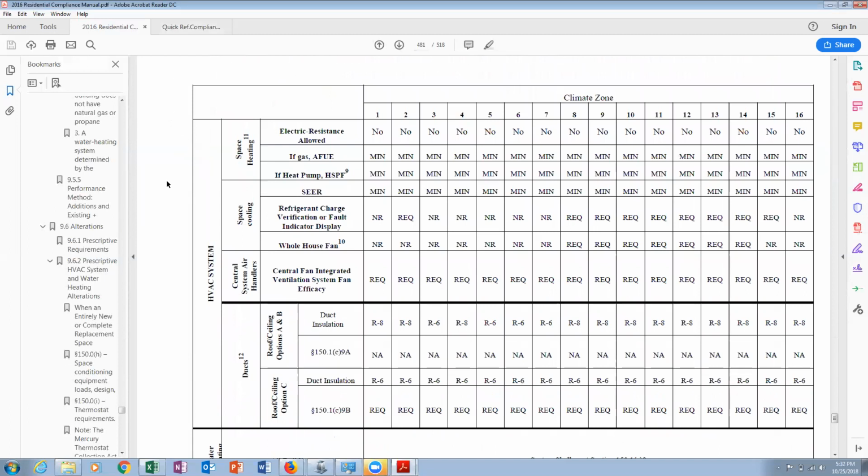You got your minimum SEER efficiency ratings and HSPF and AFUE for space heating and cooling equipment. That's for gas systems. The annual fuel utilization efficiency. Basically, it's like between 0 and 100% for the efficiency. So I think mandatory federal minimums are like 68% efficient. And I think the most efficient that they have is like 98% efficient for space heating.